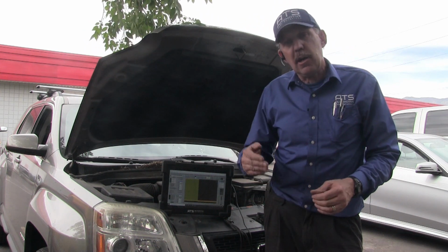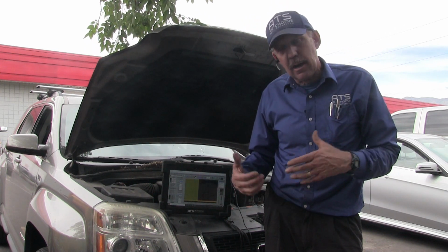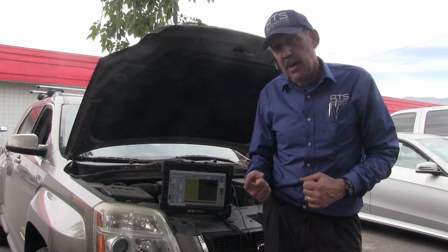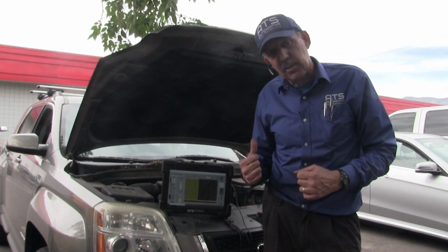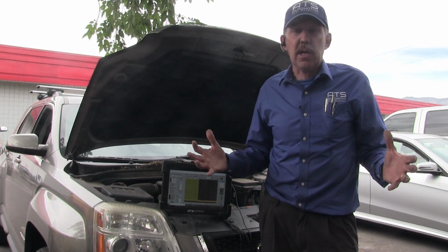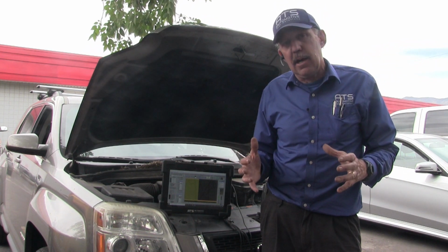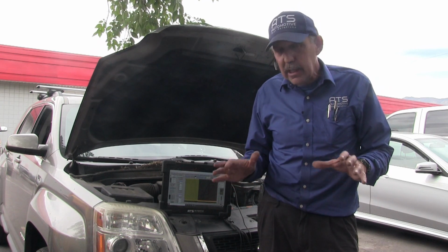If the O2 is moving up and down like this and I'm adding a lot of trim, it should be at stoich if it's reading right. If something's wrong with that O2 circuit, the feedback circuit, it can't be at stoich anymore. So if I have a gas analyzer, all of these fuel control problems become really easy.